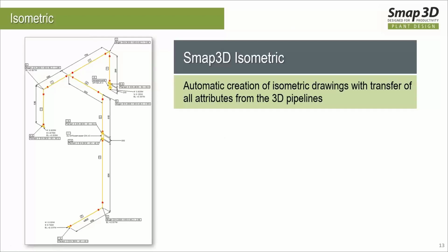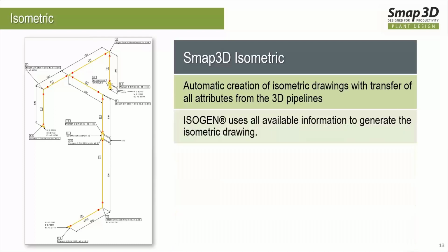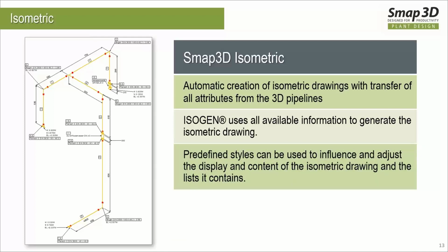And a lot of times this is a requirement by the pipe fitters or the shop that you're working with, where they say that they have to have these drawing files in this format, right? And so we do use the isogen technology, which has been the industry standard for many, many years. They've been around for about 40 years and very standardized and a common tool to use for that.